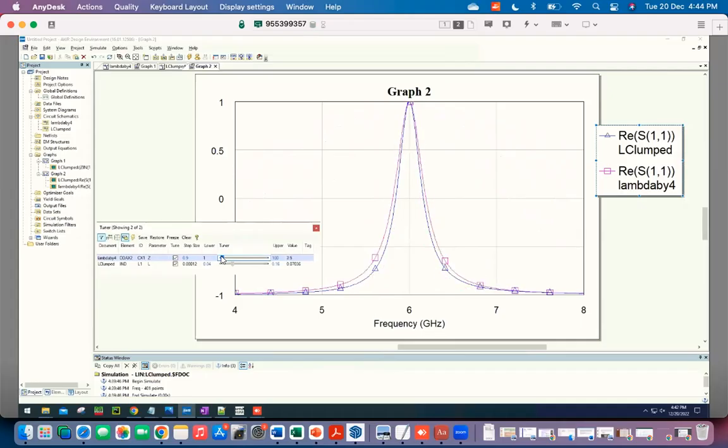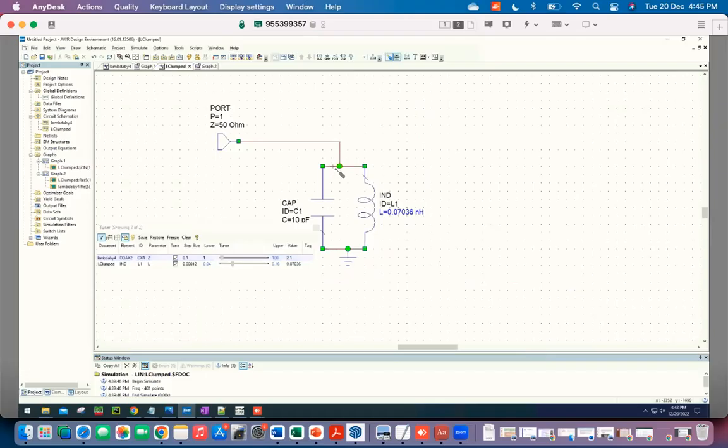So somewhere around there, where it's about 2.5 ohms. That's better. Almost exactly match. Saying 2.1 ohms. So it's saying I have to design a transmission line whose characteristic impedance is 2.1 ohms in order to get the same LC resonator as I have